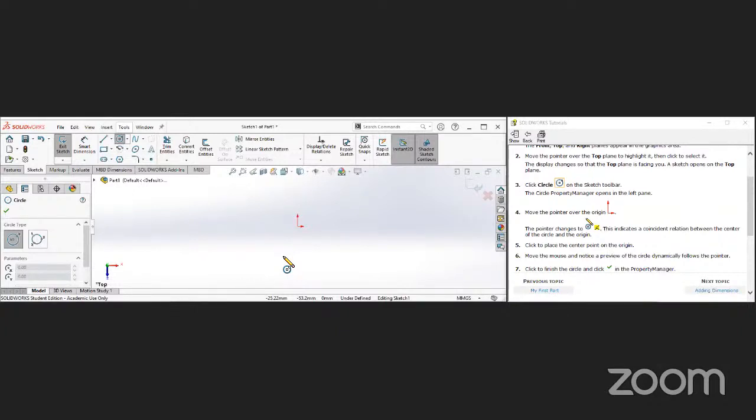In order to fully define a sketch, we have to specify every dimension on it, every length of every line, every width, where all the parts are. And it makes it safe, so we can't accidentally click something and drag something around. And also communicates our design intention for anyone who's trying to look at our sketch.